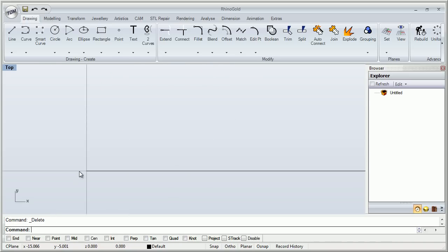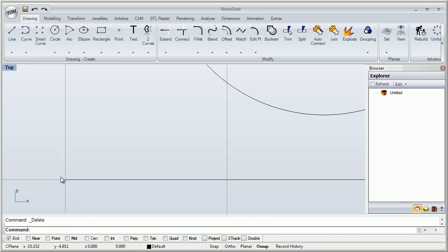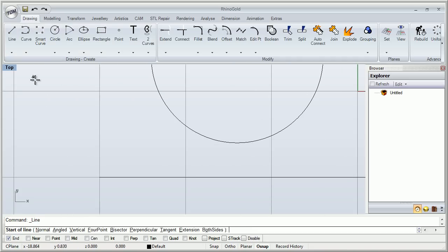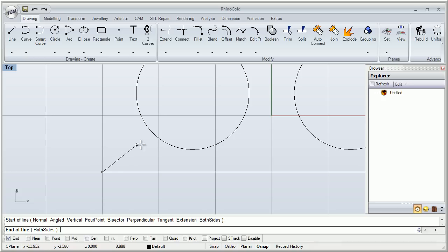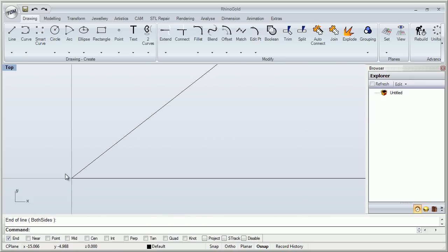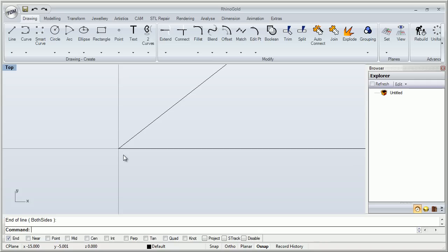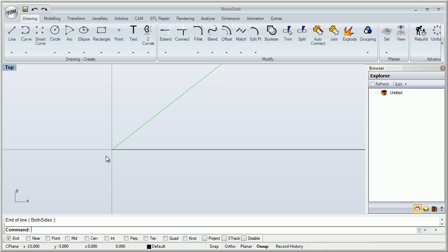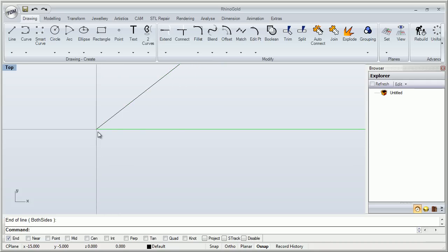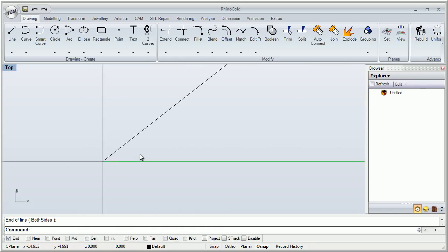So let's activate the End tool and start drawing another line. Once again we click, putting my cursor next to the end of the line, and this small word End appears, and we click on it. Now I can be really sure that the first point of my line is exactly at the end of the other line. That's what the End reference is for.